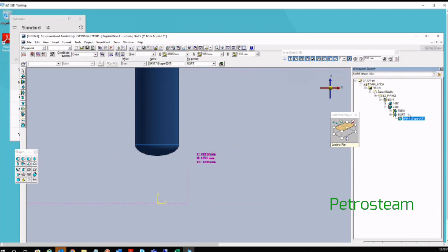Position is required only for shapes, equipment components and equipment, not for the design solid as it is. If you want, you can give a name to the design solid, or else by default it will take some random default naming. You can name it relevantly as per your requirement so that you can identify it properly next time. Now you have placed the design solid. How will you place a skirt?